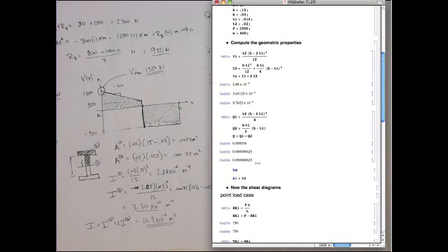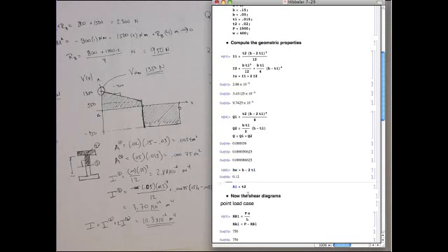HW is going to be the total height minus 2 times the thickness of the flanges, which is T1. And so that gives me 120. That's what I expected. The area of cross-section 1 should be T2 times the height of the web. And does that confirm what I got? Okay, that matches with what I have here.